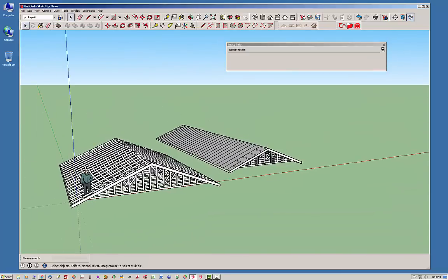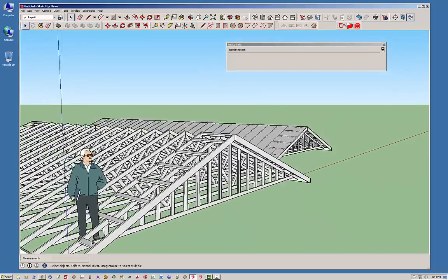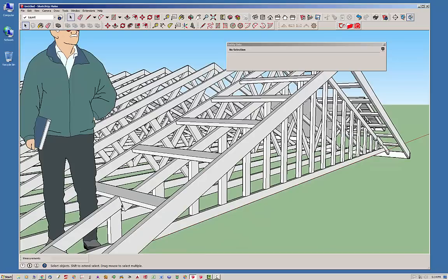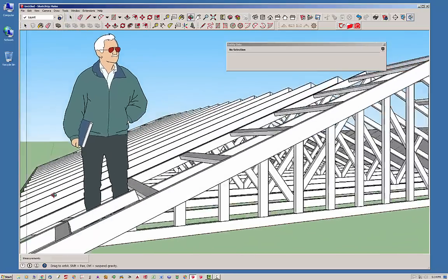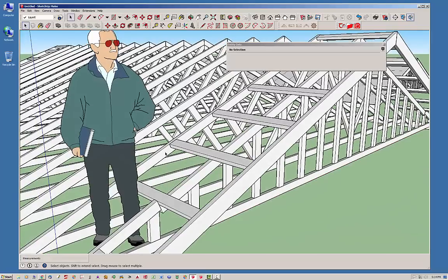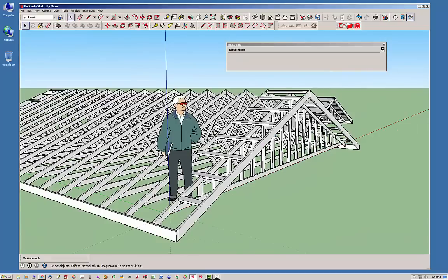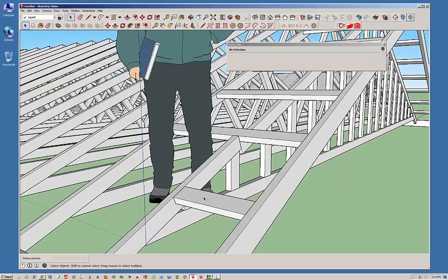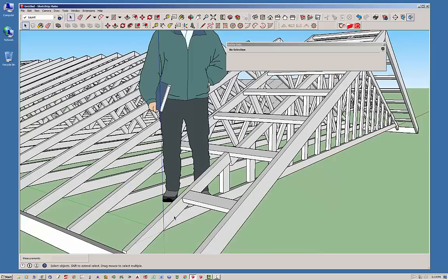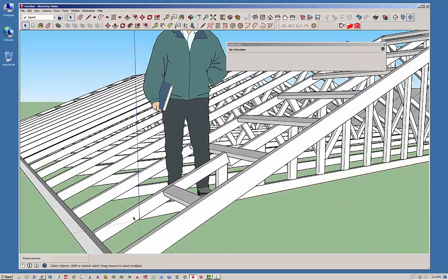Okay, so let's take a look at the geometry now. With the structural outlookers, what that option does for you essentially is it drops the top chord down to allow the outlookers to pass over the top and to contact and anchor back with the next truss, the next common truss. And right here you'll notice that this one terminates short because we don't want it to notch the truss near the heel of the truss. Otherwise it weakens this overhanging portion of the gable end truss.